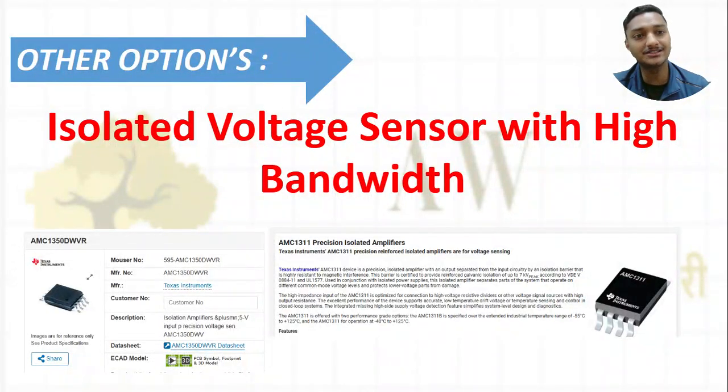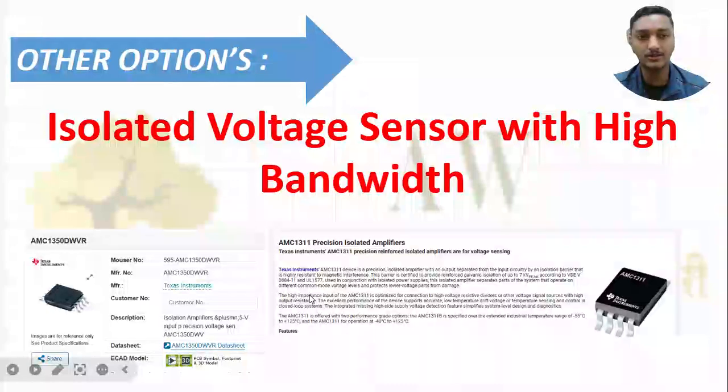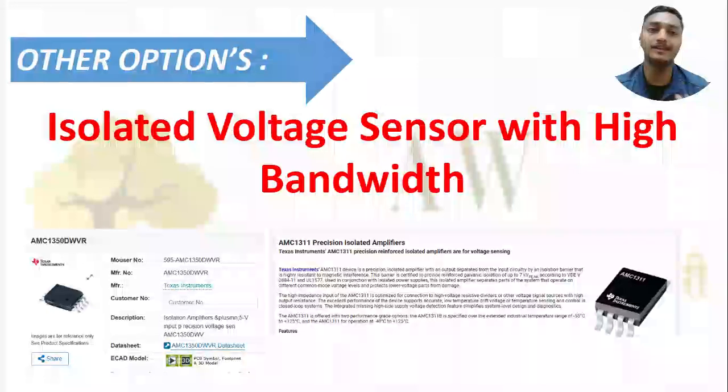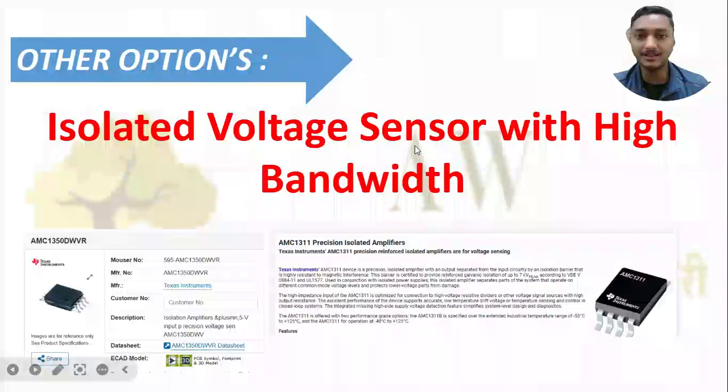But isolation is there. If you are working on 10 kilohertz, 20 kilohertz, then it is fine to go with this particular isolated voltage sensor. These have the bandwidth I told you, 300 to 400 kilohertz, but you can use them if you are working on a 10 kilohertz, 20 kilohertz application. But for going to 100 kilohertz, 200 kilohertz, you need a very high bandwidth voltage sensor. Okay, so this is another option.